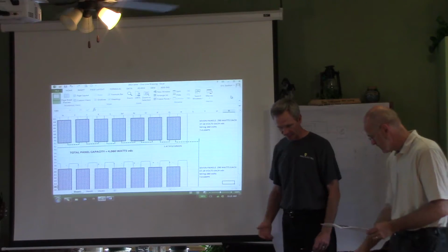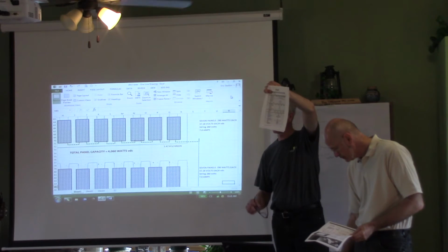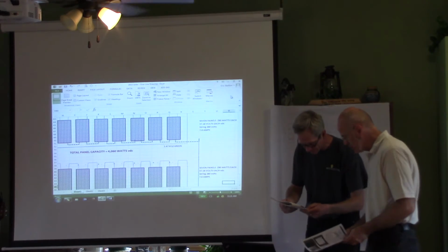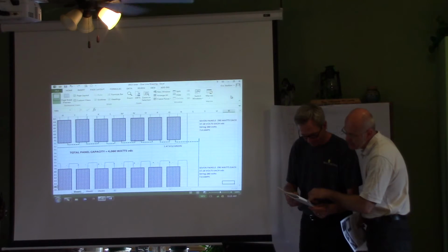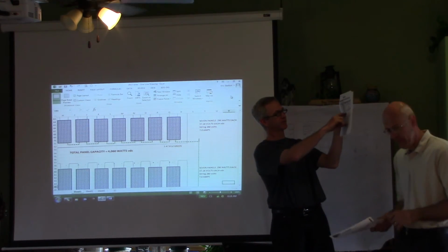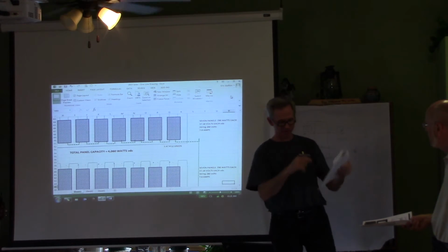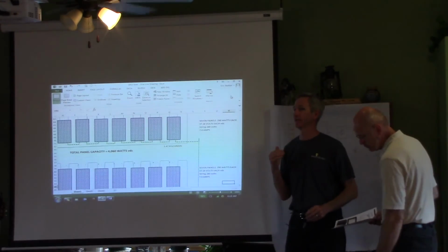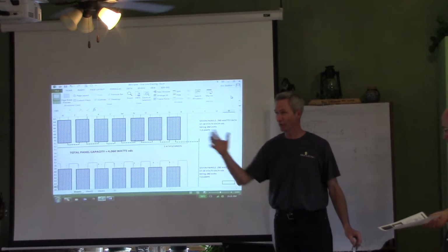If you look at the inverter specs, the Danfoss sheet, we should find something similar. 37 times 14 is 518. 518 is above your normal operating range DC, which goes to 500 volts. In the second section where it says DC, the third item is normal operating range DC, between 230 and 500. When I was talking with Dave on the phone, he said we have to get to 230 to make it turn on, and we can't go over 500. So we've got to hit a sweet spot.